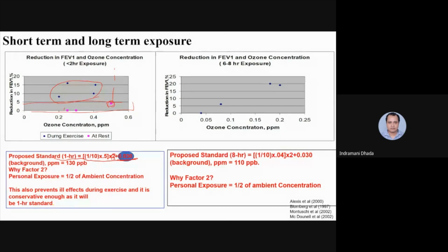Suppose we are preparing a standard. We know that throughout the atmosphere, everywhere, if you measure the SOx concentration, it is 40. You cannot find a concentration below 40. That means the atmospheric baseline concentration is now 40 ppm. Then you can permit 45 or 43 or 46, whatever is beyond 40. That is 6 ppm. If you are permitting 46, then 6 ppm is the permissible, 46 is the standard, and 40 is the baseline. Baseline means that of that area.